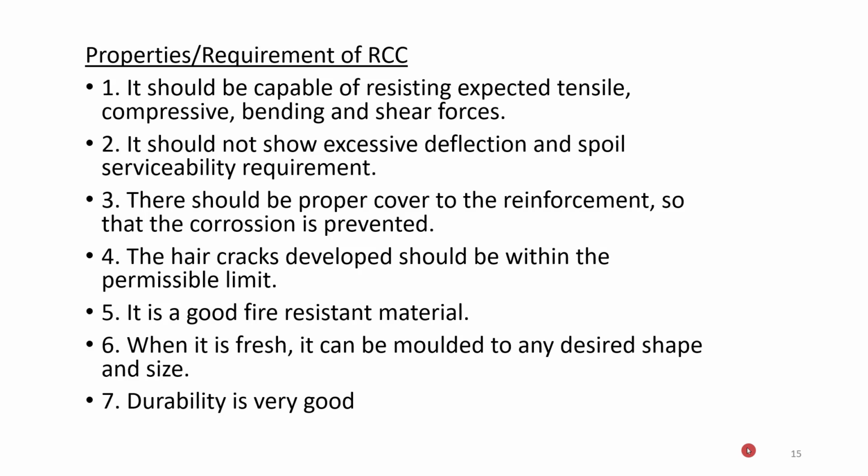There are some properties or requirements for RCC. That means RCC, or reinforced cement concrete, is expected to take tensile, compressive, bending, and shear force because we are reinforcing it with steel. It should not show excessive deflection on serviceability. When we load the beam, it should not deflect too much.